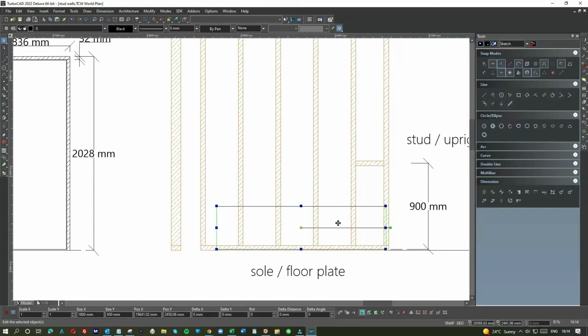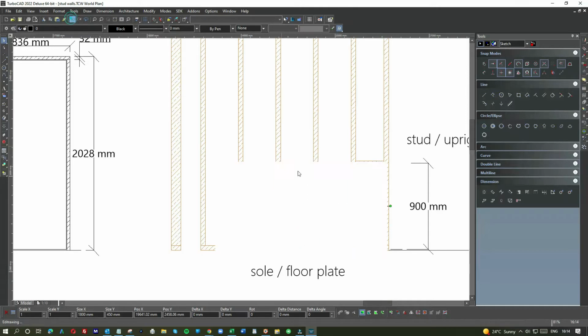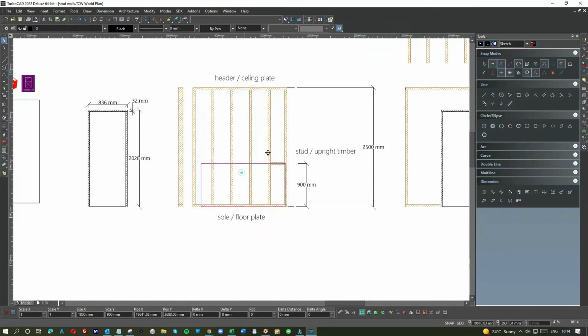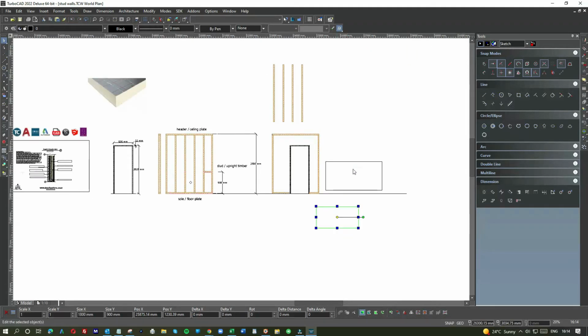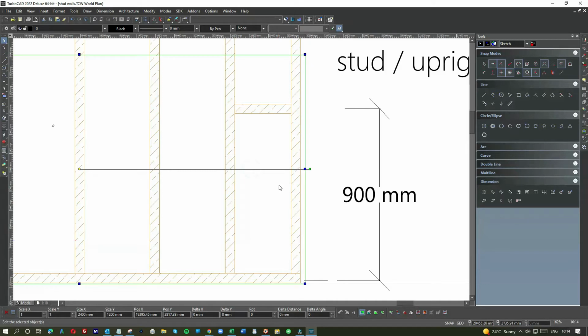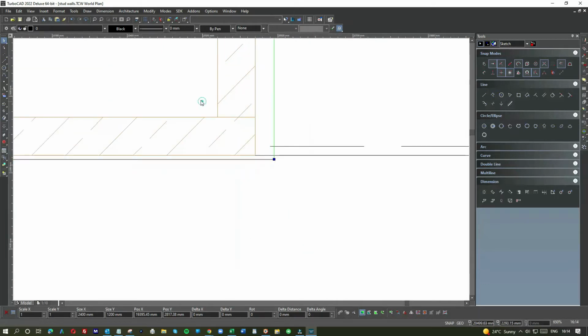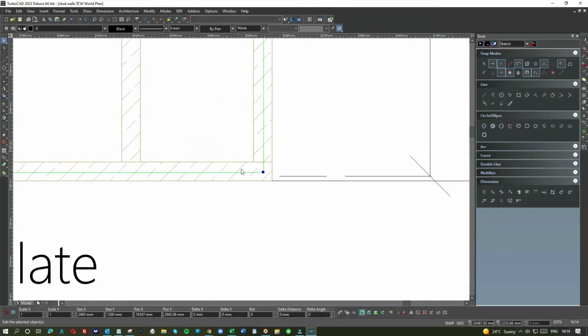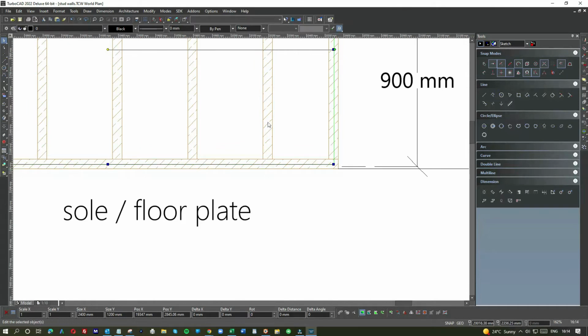Likewise, if we were doing the larger sheet of plasterboard, we would do something very similar. So generally don't put it on the floor, because the floor can be out a little, and you'll find if you're slightly out of alignment, or if the floor is running out, you're going to end up having to cut the plasterboard at the bottom, maybe at the other side of the room.